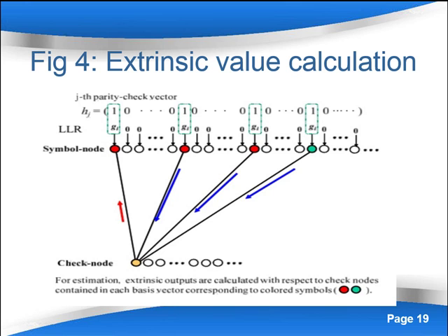This idea suggests that the extrinsic outputs would take the highest value when the phase sequence is correctly removed. So it is expected that the correct phase sequence is estimated by comparing the decoding result of the received sequences multiplied by each candidate phase sequence.